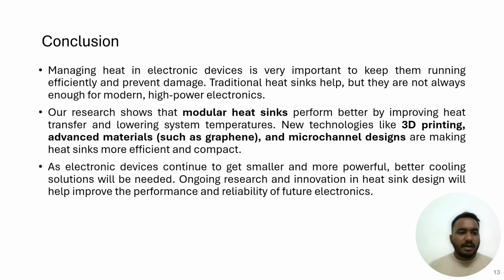The second one is that our research shows that modular heat sinks perform better by improving heat transfer and lowering system temperature. New technologies like 3D printing, advanced materials such as graphene, and microchannel designs are making heat sinks more efficient and compact. And the third one is, as electronic devices continue to get smaller and more powerful, better cooling solutions will be needed. Ongoing research and innovation in heat sink design will help improve the performance and reliability of future electronics.